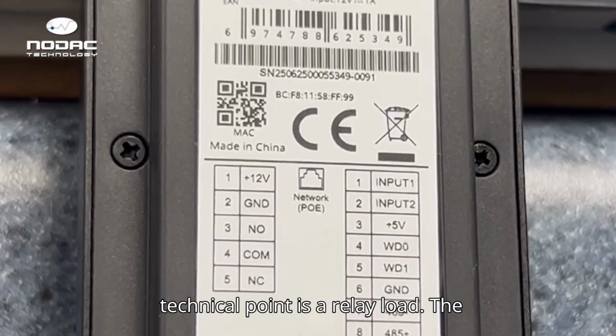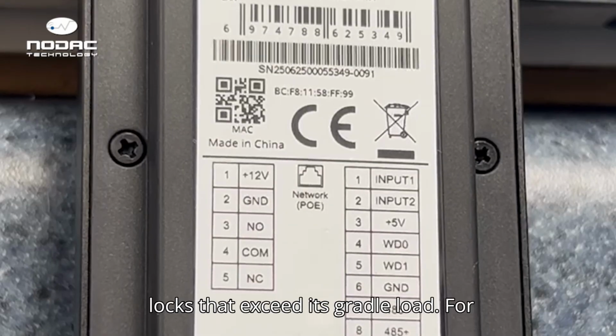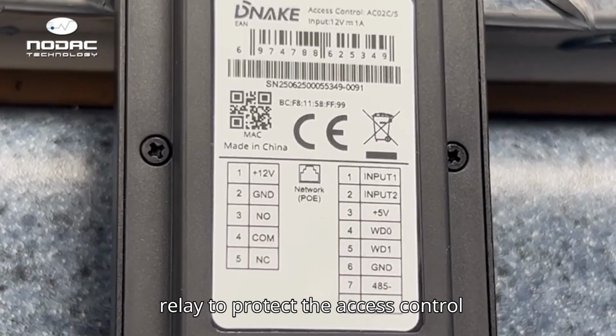A key technical point is the relay load. The relay must not be used to directly power locks that exceed its rated load. For higher consumption locks, use an independent power supply or an auxiliary relay to protect the access control terminal and ensure long-term reliability.